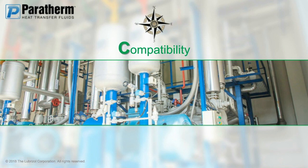Degradation and maintenance contaminants are incompatible with most fluids that you have in there. They're going to immediately degrade the fluid that you have in there, and they could possibly cause issues. Water is another serious thing that you need to look at. If your previous fluid was an aqueous-based fluid, a glycol or brine fluid, and you're switching over to a non-aqueous fluid, that is a pretty intensive application to undergo.